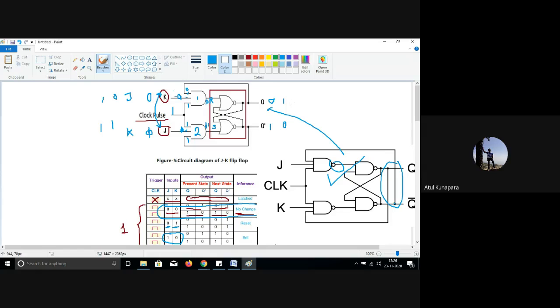It is not there in the D flip flop or RS flip flop, because in that case no invalid inputs are allowed at the input side. But here in JK flip flop, you can apply both inputs 1 1 also, and that is going to do what? Sorry. When both the inputs are set to logic 1, your output is going to toggle.